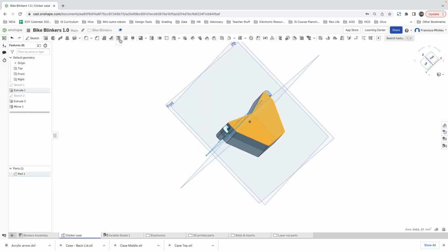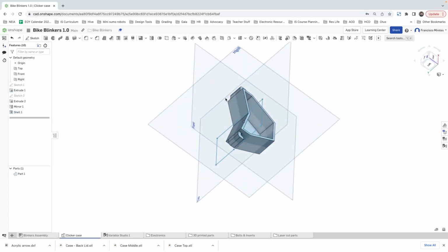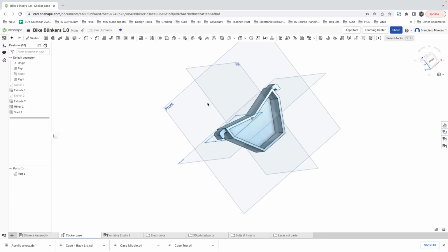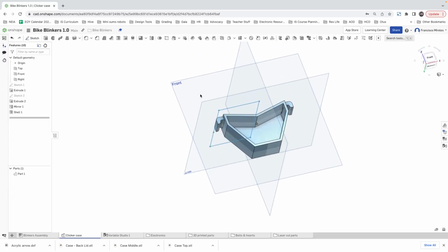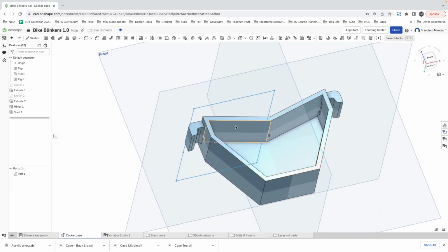Now I'm going to make it hollow. So I'll select this face. I'm going to say shell 2.5. I think that's good. Yeah, 2.5 is good. Let me just check. Yeah, 2.5 is good. Awesome. We're almost there, as you can see. Good. I just need a...